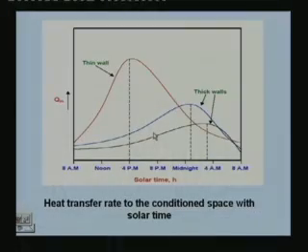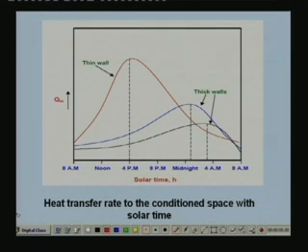Let me show a typical variation of heat transfer rate. This graph here shows the heat transferred to the conditioned space. Not heat flux, but total heat transfer to the conditioned space as a function of solar time, for a thin wall, a thick wall, and a thicker wall.